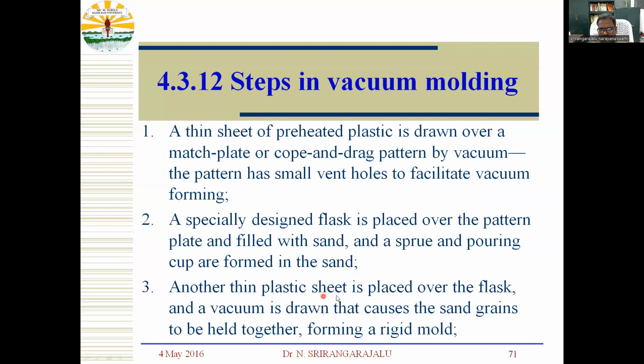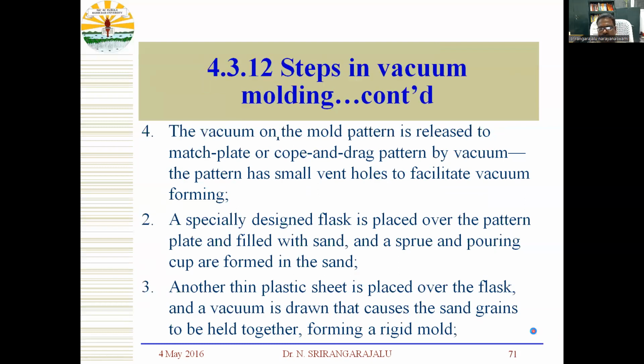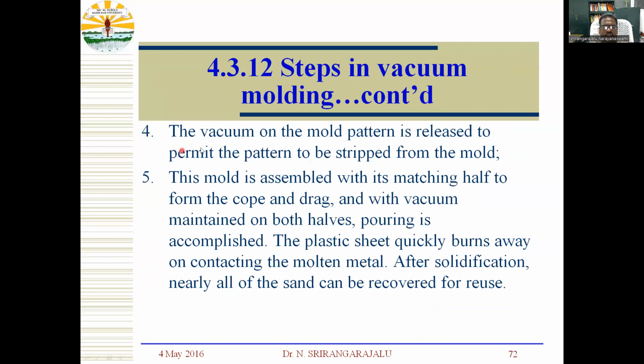Another thin plastic sheet is placed over the flask and a vacuum is drawn that causes the sand grains to be held together, forming a rigid mold. The vacuum on the mold pattern is released to permit the pattern to be stripped from the mold. This mold is assembled with its matching half to form a cope and drag, and with vacuum maintained on both halves, pouring